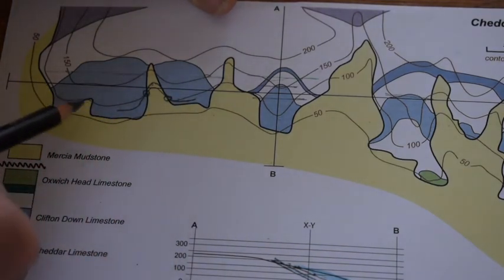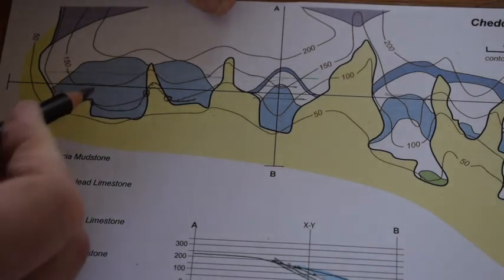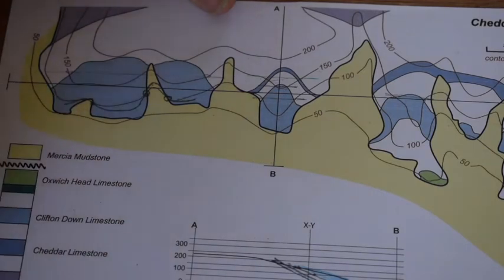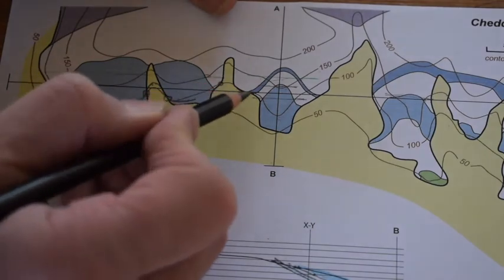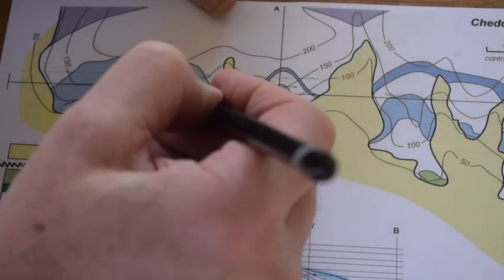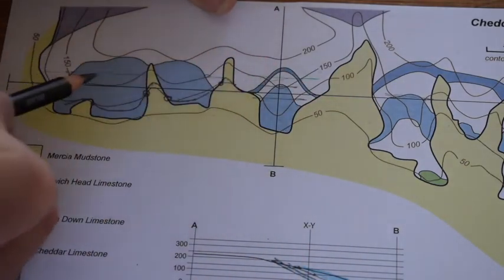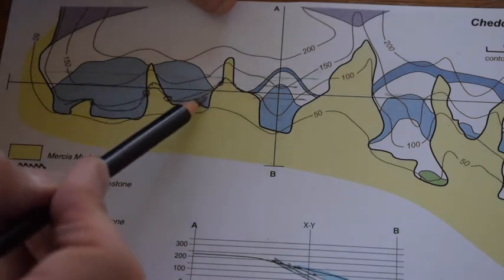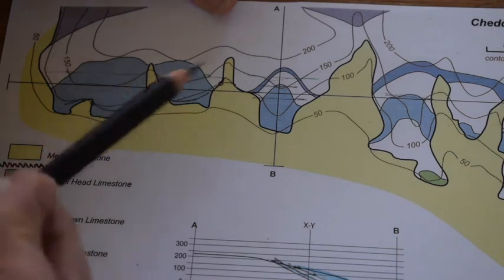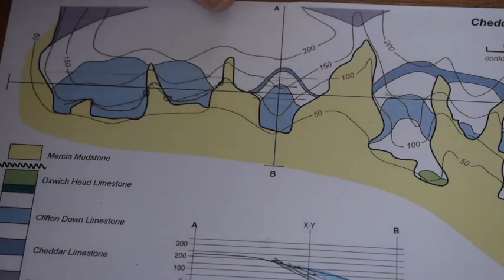Let's keep going. And in this position, we can see 2 other points on the 100 metre topographic contour, and we can take that around like this and out, and then in and around like that, and so forth. How about over here? There is the 100 metre contour. So the structure contour is going to come around like that, go into the subsurface and back out again. So I have this general bow shape in and out, constrained by the outcrop positions and by the positions of the adjacent topographic contours as well.